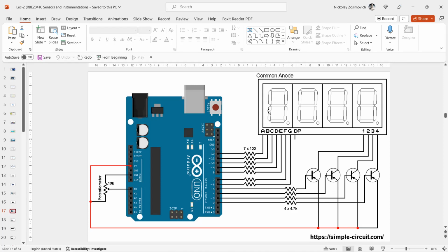It is possible to achieve higher sampling rates using different implementations in code, for example. The reference voltage for the internal AD converter can be set to an internal 1.1 volt reference, the default 5 volt supply reference, or an external reference.